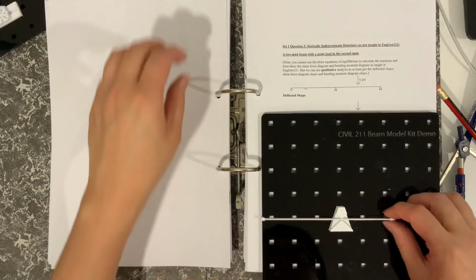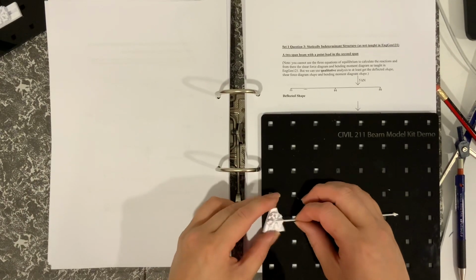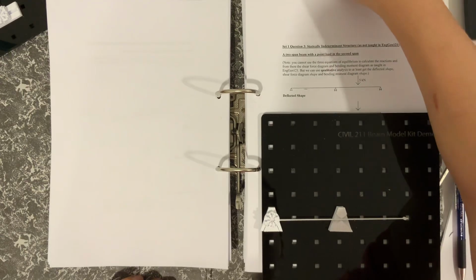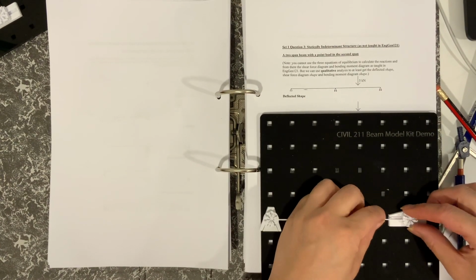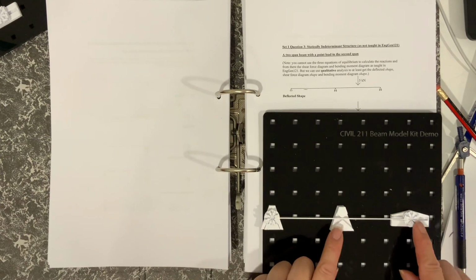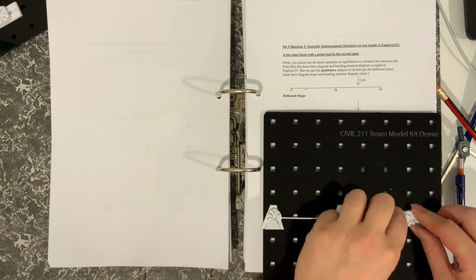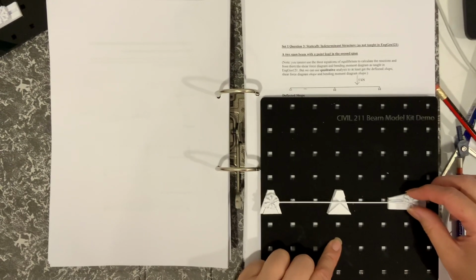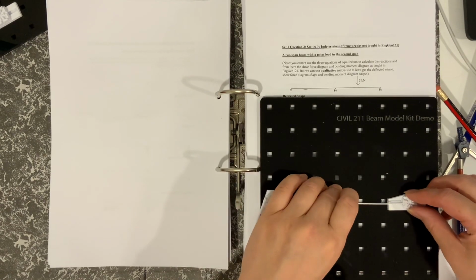So we started off originally with the roller, and then an internal one, and then another one, and here I might use that one there. So this and this are the same. It allows rotation around there and there, but it doesn't allow it to move up or down, and this one doesn't allow it to move up or down, but you can have sliding over here.